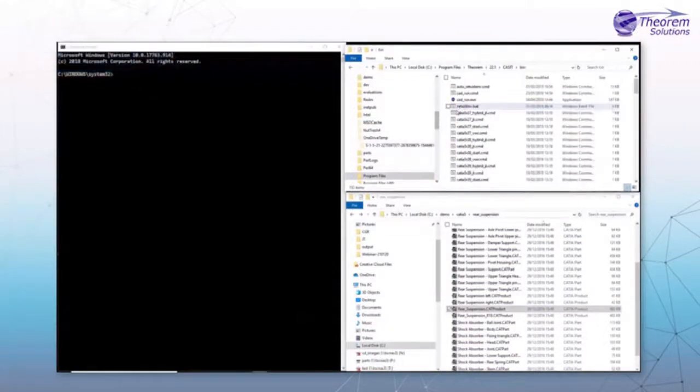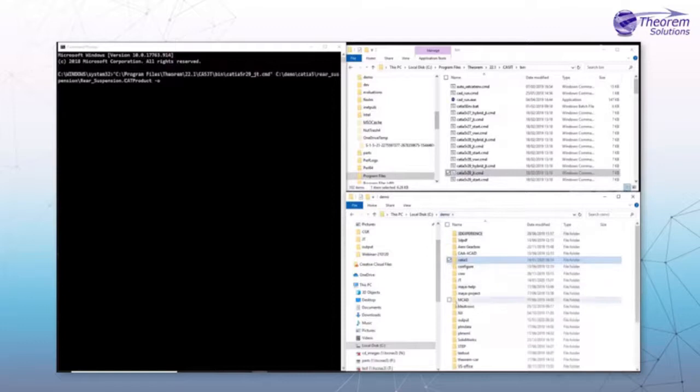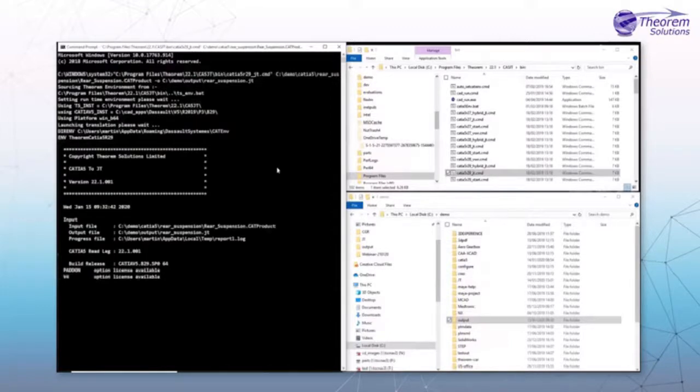And finally, a view on the command line running. Again, this is, I guess, the most pictorial way we can demonstrate automation and inclusion of these translation processes as part of a process or an automated scripting utility that you may or may not have in your organization at the moment. So it's really showing that we've shown the most basic from the CAD system plugin. We've shown the next level, which is using Theorem's provided UIs, doing a translation. And this is, if I was to programmatically write some software to call the translation, what can be done? And obviously running that in the command line, you can see there, you get the command files, you get the log files, you get the completion status.